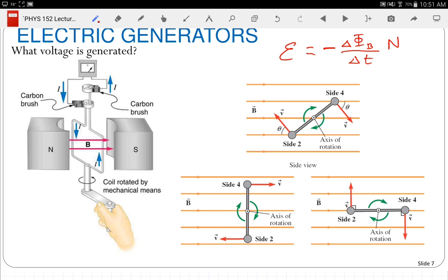The whole derivation here and going to the next pages was calculating, okay, what's the motional EMF produced on each of the 4 wires? And it turns out only 2 of them have a motional EMF induced. And then we take, okay, so one EMF is this way, one EMF is this way. They're in a loop, so they add together.